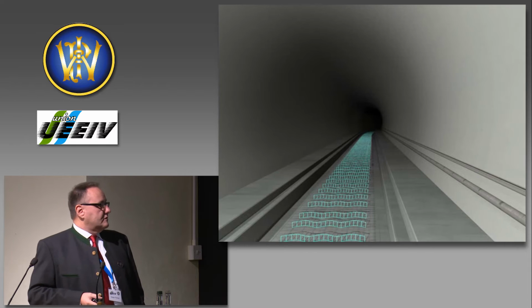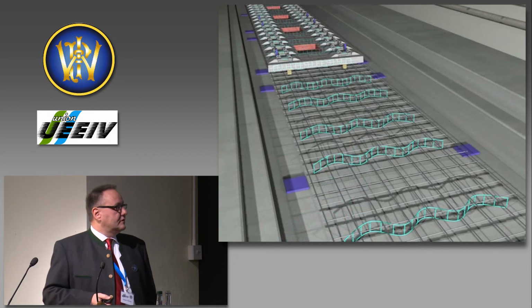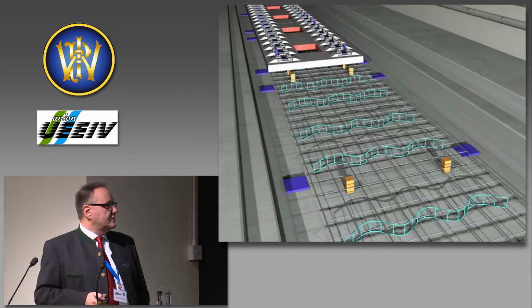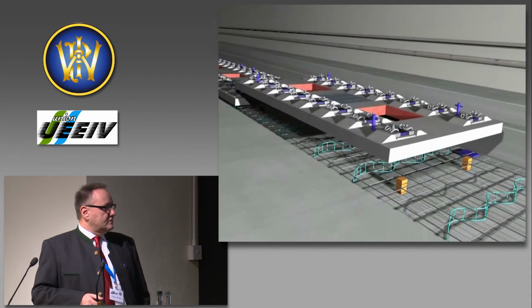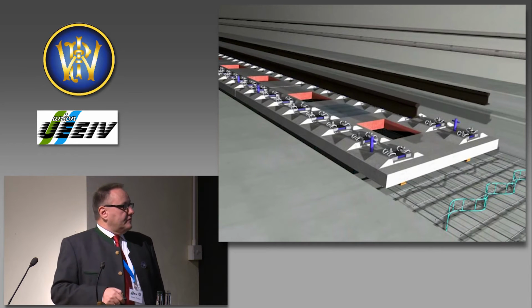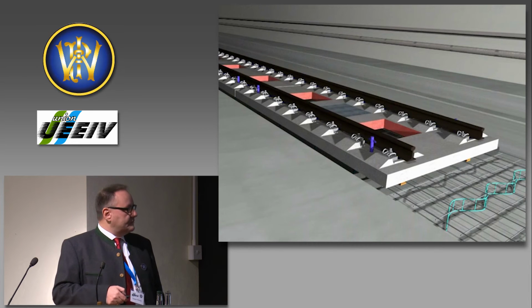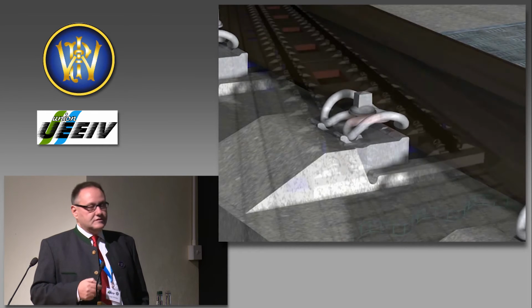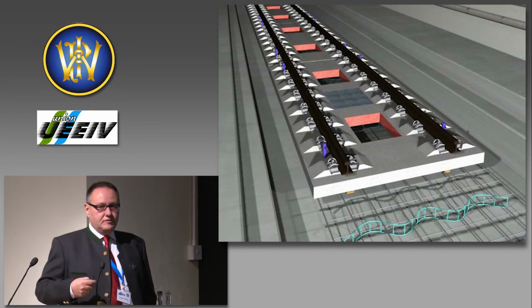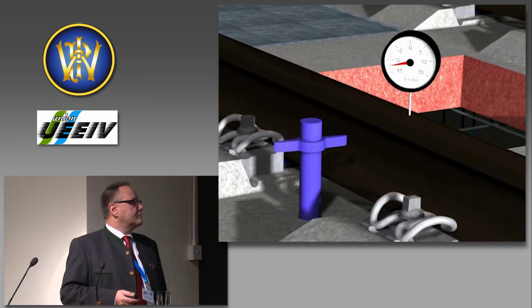If you look at the construction, it's very easy to install the system in a tunnel, for example. We need some reinforcement for the underpour concrete, and the precast slabs are put into position. There are spindle holes on these slabs where we can install the system in the exact position. We are using the final rails normally to put the track into the correct position.